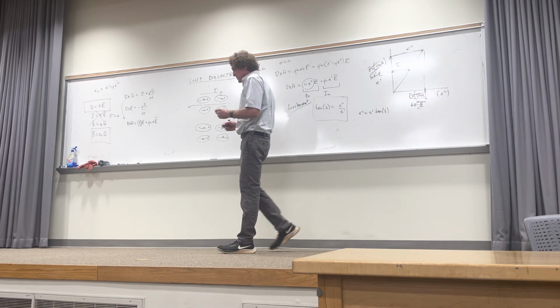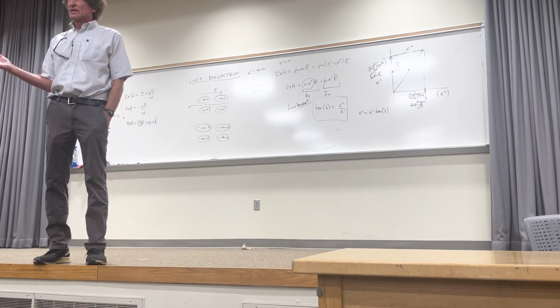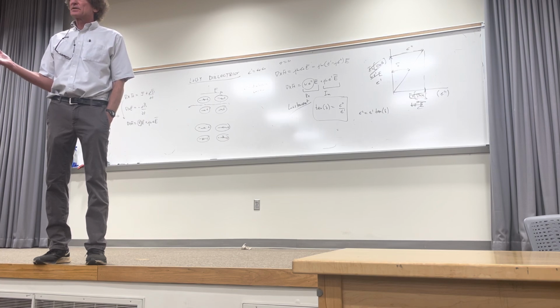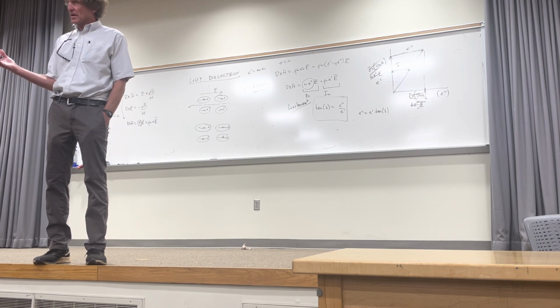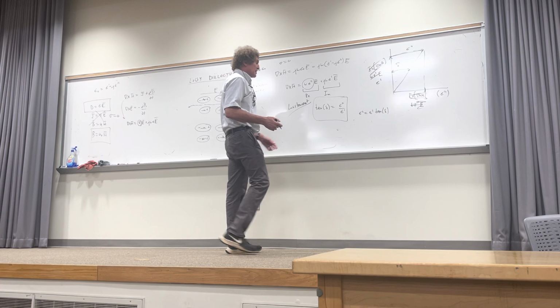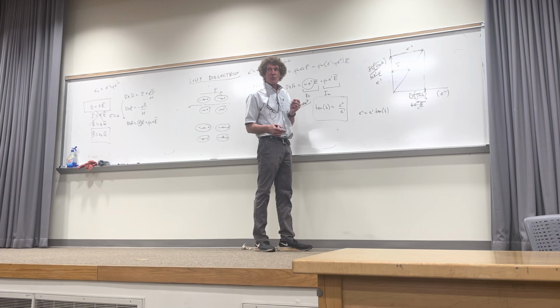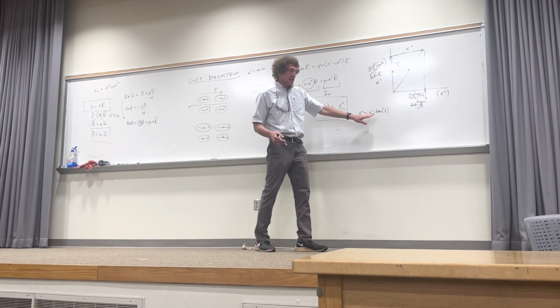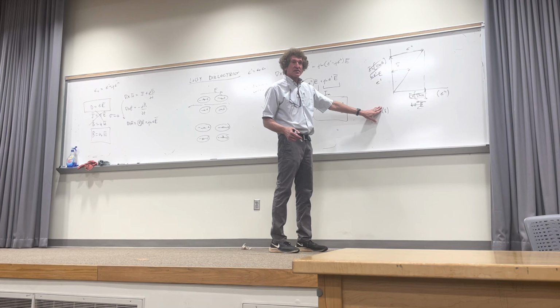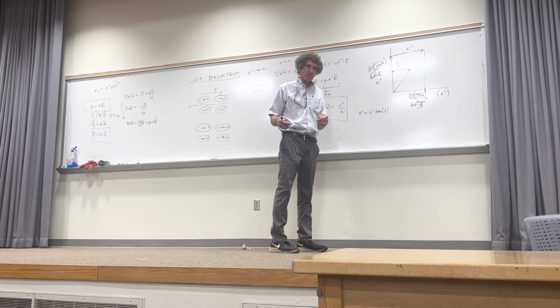And the truth is this: what do you know about tangent of very small angles? Tangent of x is about x if x is small, right? Do you all remember that? Same as sine of x is about x if x is small. That has to be in radians, by the way. So if you're talking about something with a loss tangent where that angle is less than a degree, then you don't even have to take the tan. You can just put the angle in radians there times epsilon prime. But usually what they give you is the tangent in the tables.